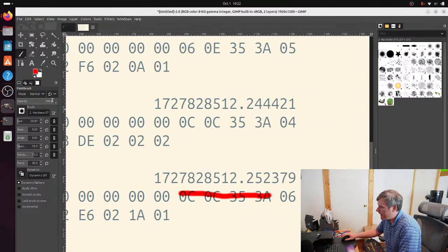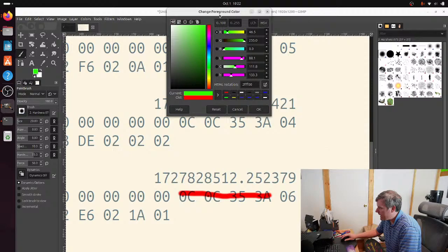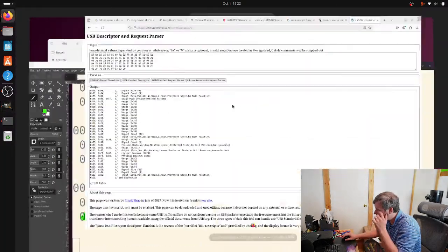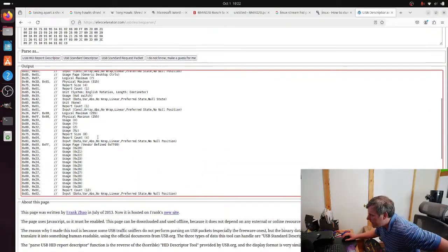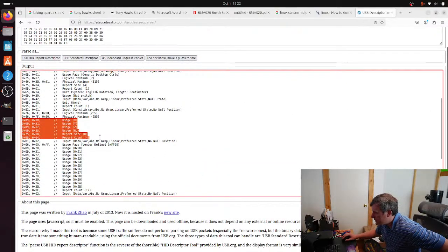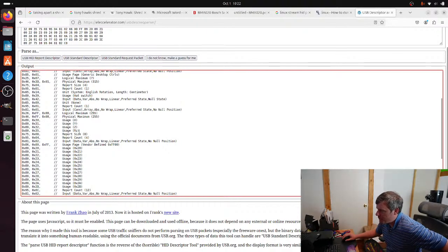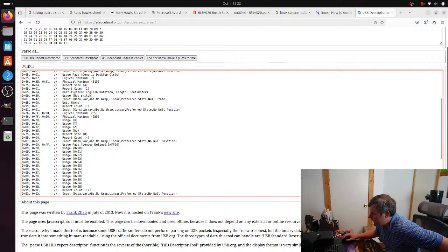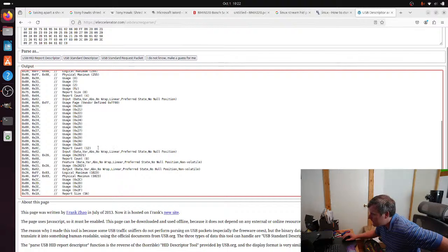I'm now trying to figure out what exactly these do right here. Because if we come back to the HID report, we can see there are right here these report size of 8, report count of 4. And it's labeled as a usage as XYZ, RZ. I think that's just wrong. Those are the 4 light sensors. And then the next input after that, we have, so it uses the same size of 8, but then there's 12 inputs there.